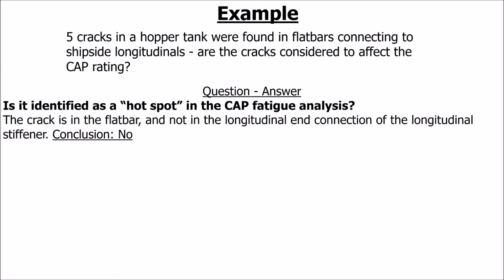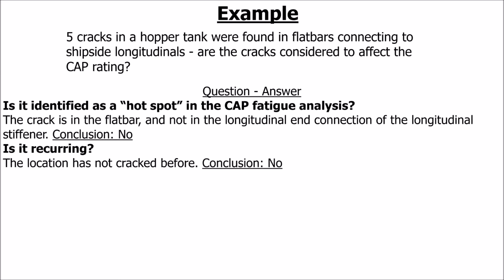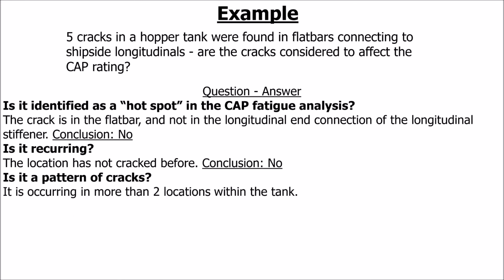The crack is in the flat bar and not in the longitudinal end connections of the longitudinal stiffeners. So, conclusion is no. Recurring, has it happened before? The location has not cracked before, so conclusion is no here. So is there a pattern of cracks? Can I find this type of cracks in more locations like this?